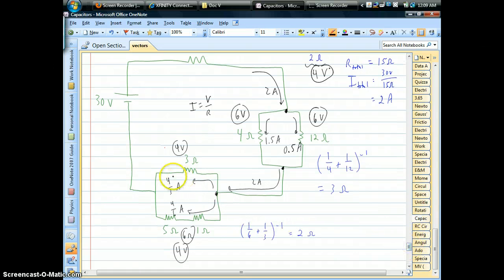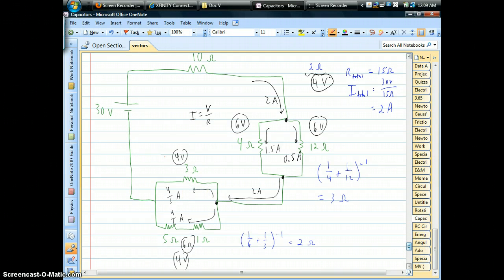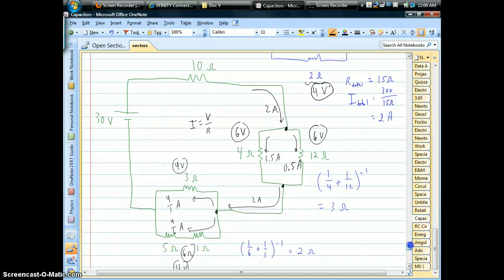So we've nailed down what the total current is, how it splits in each of these. Notice on the bottom set, in reality you have 2 resistors on that bottom branch with 4/6 amps. Well, that's going through each of those because they're in series. They have to have the same current. So we now have everything about this particular circuit.